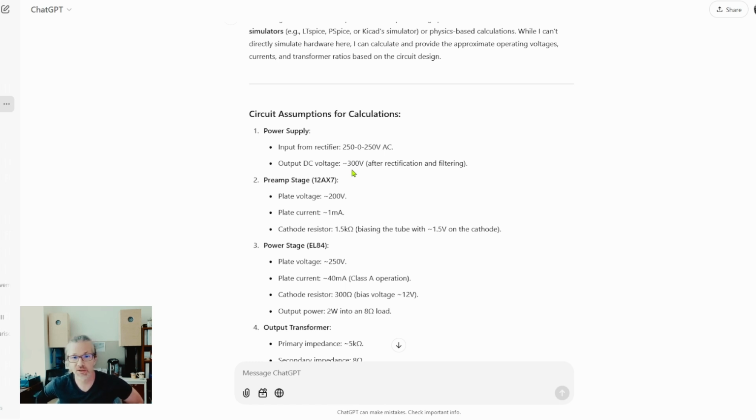People are running most of the power tubes at 100% or over 100% capacity, and that's why there's the generic problem that people have the impression that every 6 months you have to change your power tubes in a tube amplifier, because after 6 months you already notice that the sound quality is degrading, because the tubes are approaching the end of life. And not because that's how tubes are, that's how bad designs are.